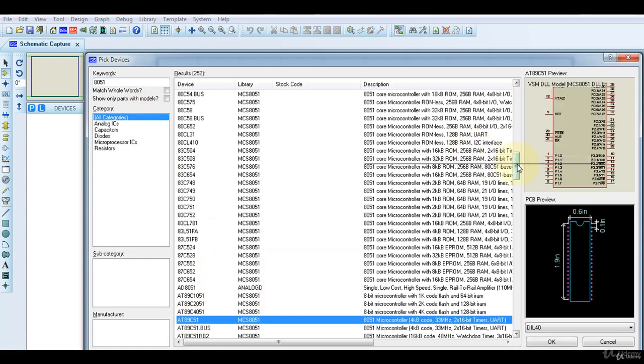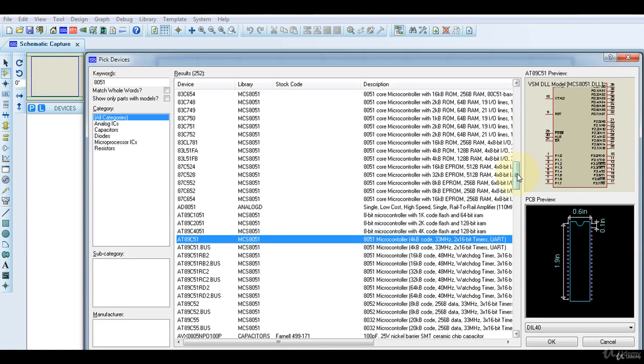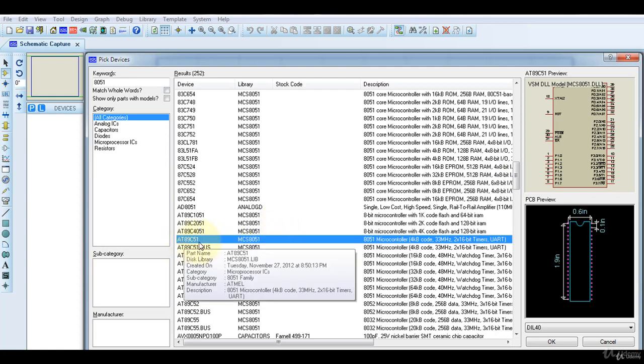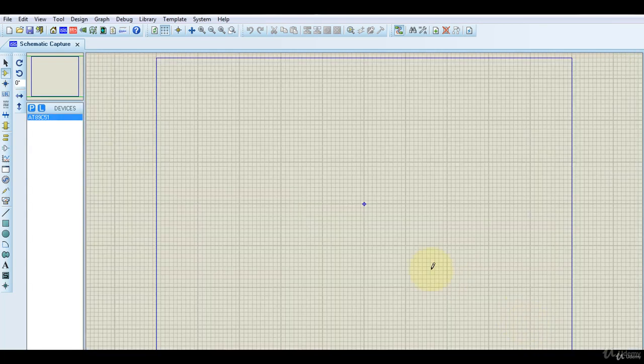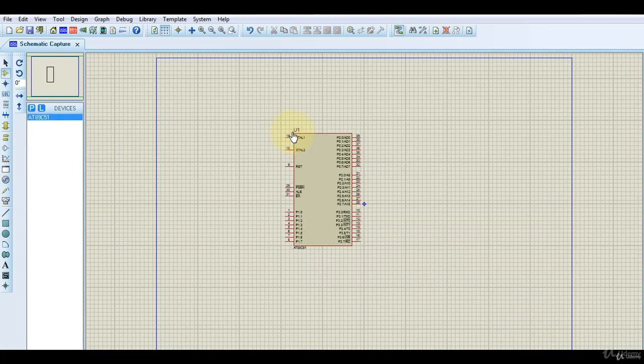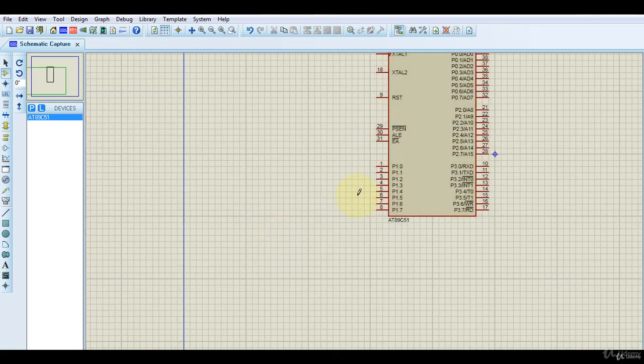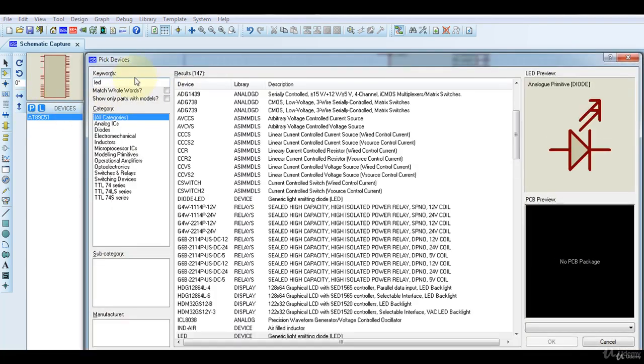The microcontroller that we used while writing code in Keil software was the P89V51RD2 microcontroller from Philips. That particular microcontroller is not present in the Proteus library, so you can use any other microcontroller also. I am using the AT89C51 microcontroller here. The code written for the P89V51 microcontroller will also run on the AT89C51 microcontroller, because the basic internal architecture of both microcontrollers is the same.